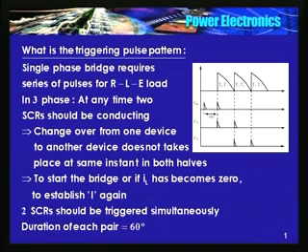See, this duration is 60 degrees. So the moment you trigger 2 somewhere here, 6 turns off and 2 starts conducting. So ideally you need to have 2 pulses which are separated by 60 degrees.